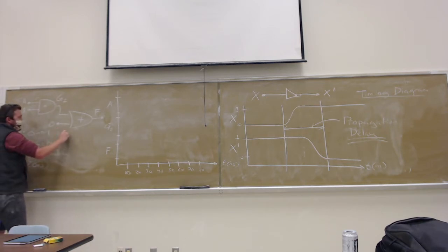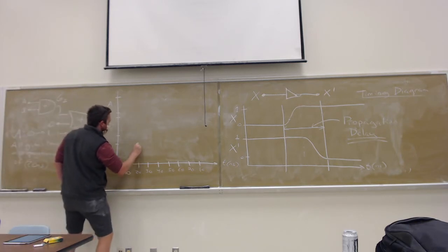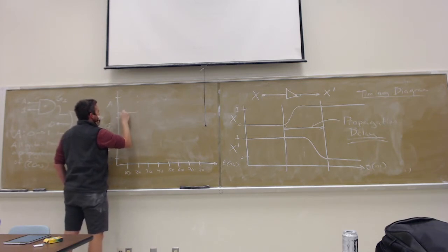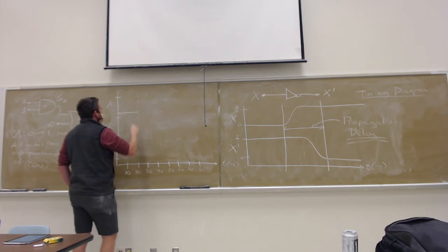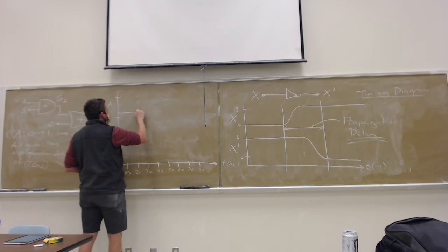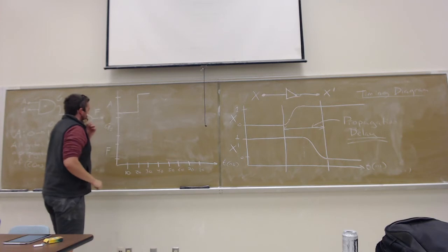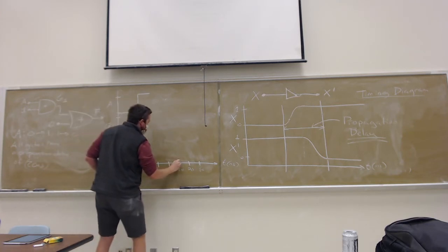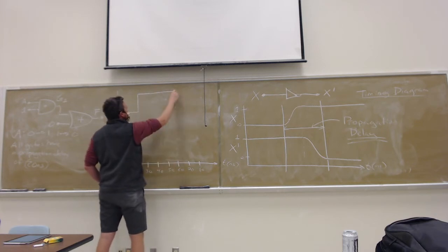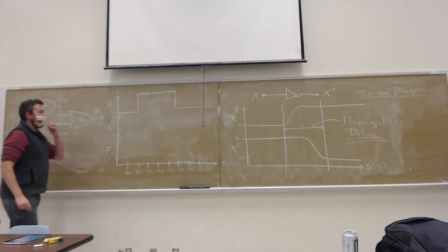Okay. So first thing is we're going to look at A as it transitions from 0 to 1, and then from 1 back to 0. So what I want to do is this. Let's leave A at 0 for 20 nanoseconds, and then let's take it to 1. And for these diagrams, we are going to forget about the curve business. We're going to draw them just as straight lines for this. And let's say that it stays 1 until it hits 60 nanoseconds, and then it goes back to 0 and it stays at 0 for the rest of our simulation time.